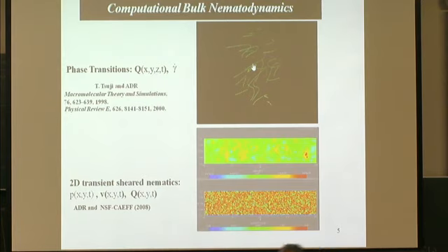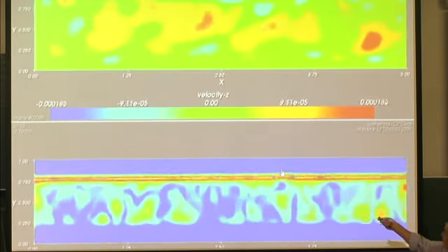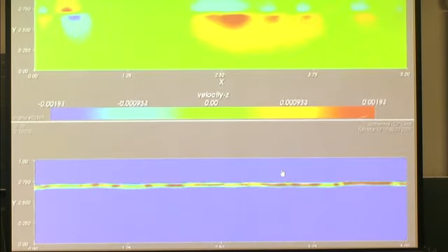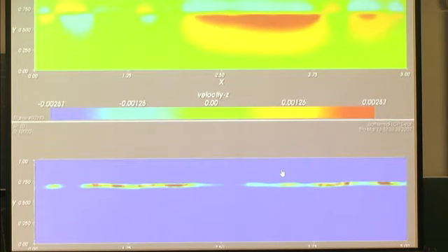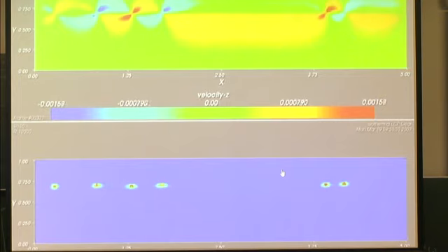And so this shows a little bit where we are. So the top figure is just the velocity in the z direction. So this red is plus, blue is minus. That gives you an indication that flows go out and into the page. So you have secondary transverse flows that have to obey mass balance. So that's why some flow is coming out, some flow is going in.